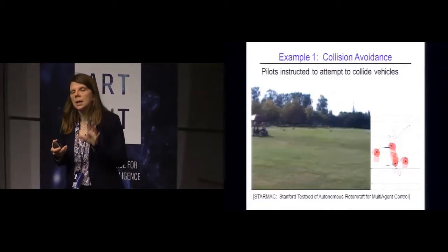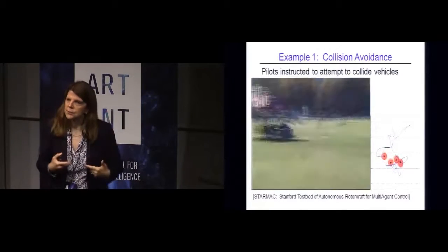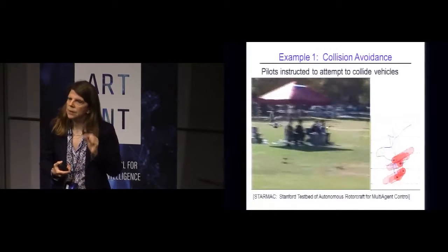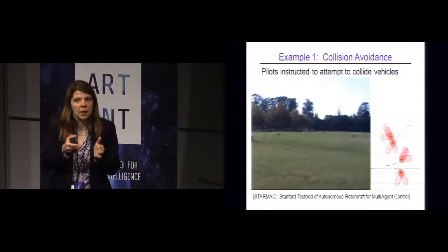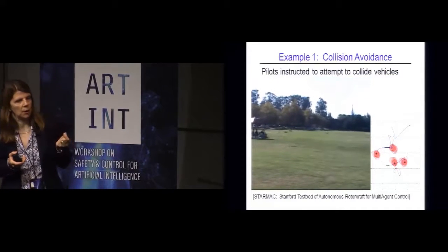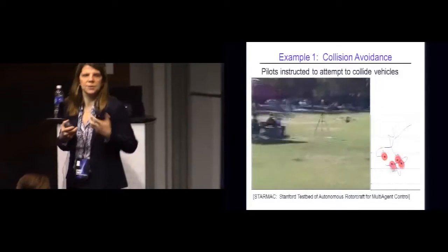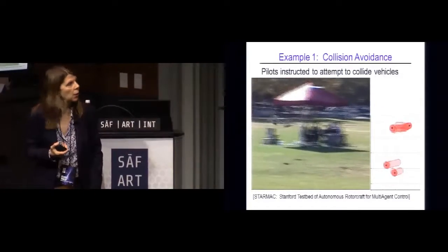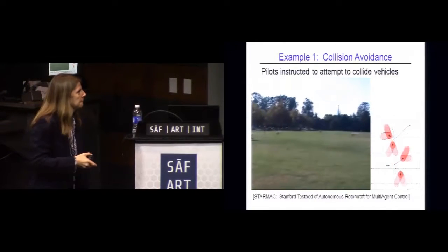Okay, and so in this case, in general, if we trust the models that we've used and we trust our computational method, this provides a verification of safety. And so, those are big ifs. We have to have a good model of the system that we trust. Typically, we use simpler models that are over-conservative. We overestimate the effect of the disturbances, the actions of other aircraft that we don't know. We underestimate the effect of control in computing these sets.